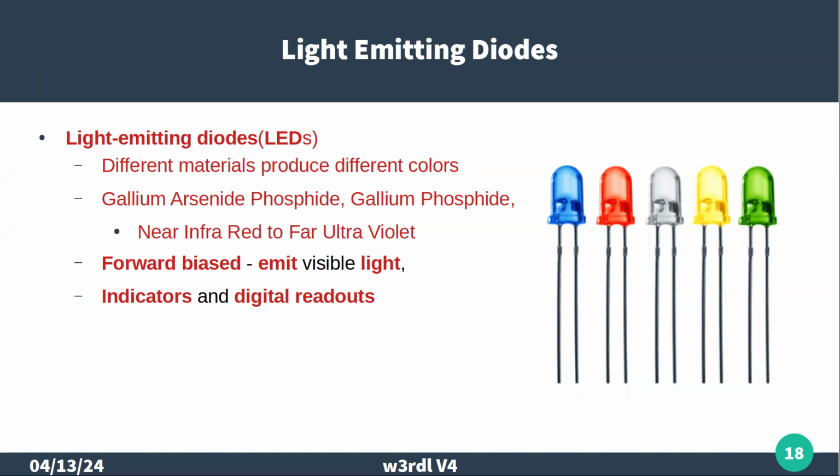So in a normal regular silicon diode, if it was in a package where you could actually see the element, it would be emitting photons, but probably not in the visible light spectrum. They learned to take advantage of this for making a light emitting diode by using different materials, which determines what size that band gap is.